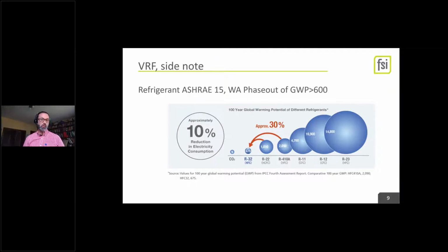In 2021, Washington State is going to have a requirement that all new buildings are heat pump based, no gas for, again, service water heating and space heating. You'll still be allowed to do industrial uses and other non-regulated uses. I think I'd say it that way.